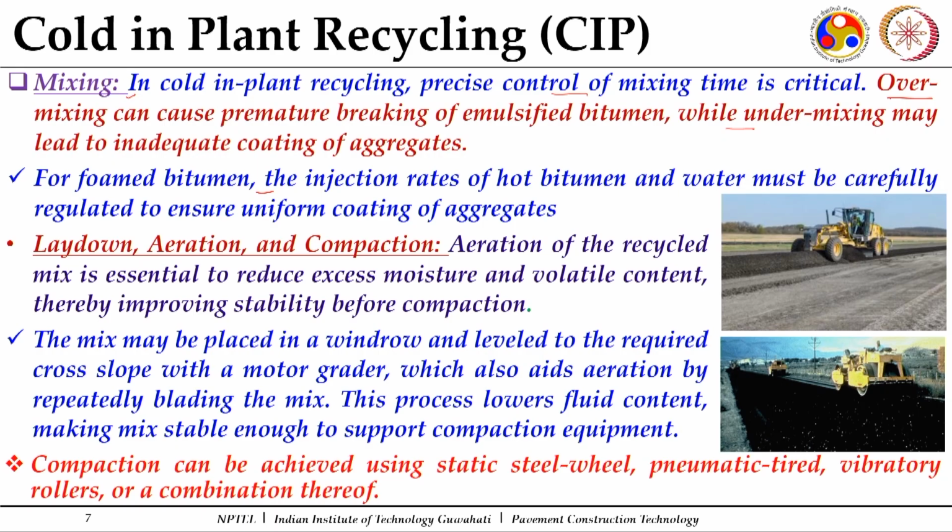Now, the important thing here is the injection rate of the hot bitumen. It may depend on the grade of the bitumen, the temperature of the bitumen, the source of the bitumen, and how much percentage of water is to be injected, which is an important aspect, because this foaming increases the volume of your bitumen. As the volume increases, the viscosity decreases, which helps us to coat your aggregates in a better manner, and along with it, in due course of time this volume will fall down.